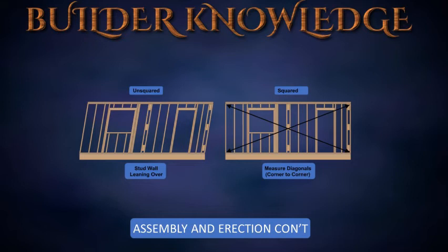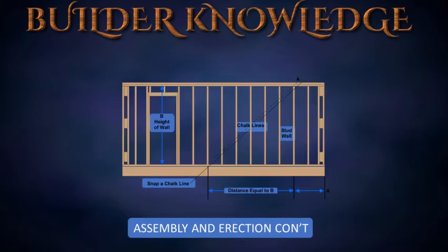Now we can install the let-in bracing. Mark the plates and studs and notch them for the brace. Tack the brace to the studs while the wall is lying on the subfloor. Reminder: tacking instead of nailing allows for some adjustment after the wall is raised. After any necessary adjustments are made, the nails can be securely driven in. Now you can place the fire blocking in the wall.